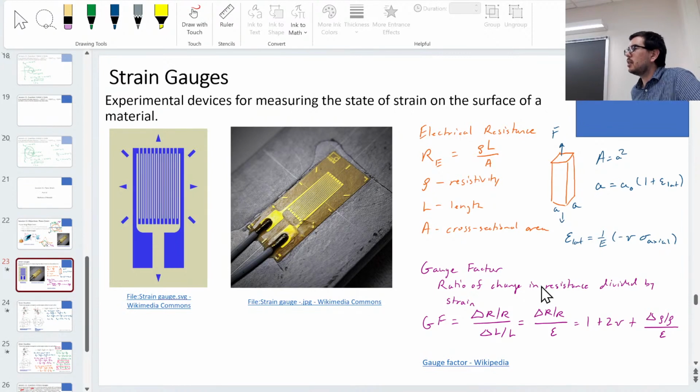Okay, so you can, yes? Does the adhesive limit the straining of the material? Sure, yes. I mean, if you had a really thick adhesive, and imagine that the elastic modulus of your adhesive was super high, and it was super thick. Or actually you could imagine if it's super low, that probably is a worse situation. Like if I put a strain gauge on a piece of rubber, and something strains underneath it, then I'm going to have no ability to measure what the strain is above, right? So you want to have really good intimate contact, almost like rigid contact, so actually a very high elastic modulus if possible, so that the strain gauge feels the strain that the object is feeling.